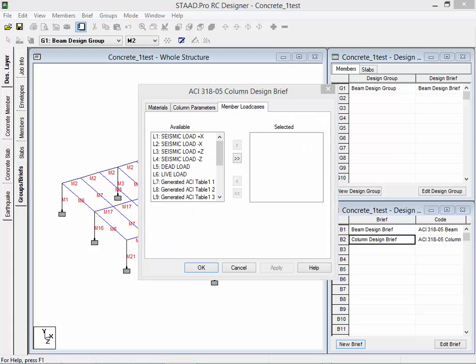The last thing we're going to do is enter our load cases. Now, the concrete columns are designed using a collection of primary load cases and combinations. Unlike the beam design, the design for columns is performed considering the forces in each case or combination, and a suitable reinforcement layout is defined accordingly.